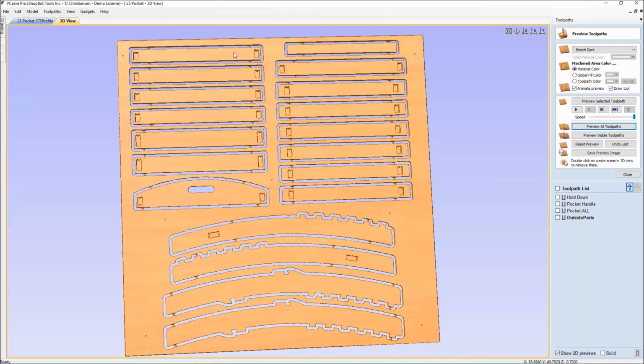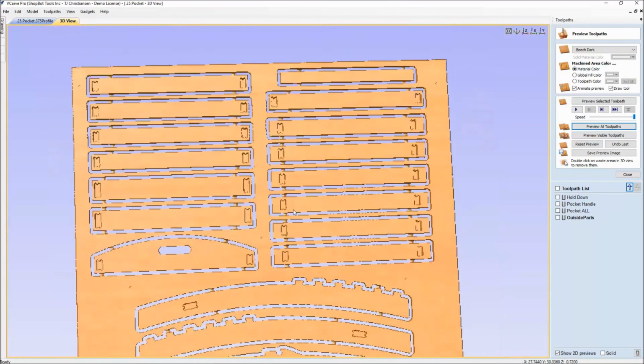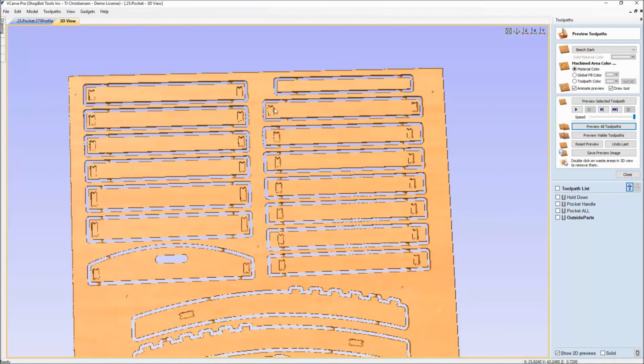So if you cut away enough material in a project like this, whatever is left for scrap will flex back and forth. So for us to fit 2 of these out of a 4x8 sheet, they had to be put together this close. So you do see a scrap clearance in here, but the tabs being all vertical, lining up with each other, they actually work for strength and structure of this part and allow that part to cut and not have any vibration or moving in there. So the tabs serve a purpose of not only holding the part to the scrap material, but they also help, in this case, adding strength to the material that's being cut away.